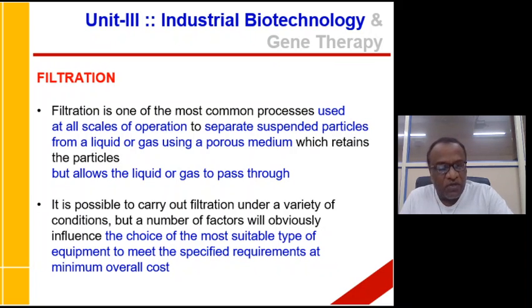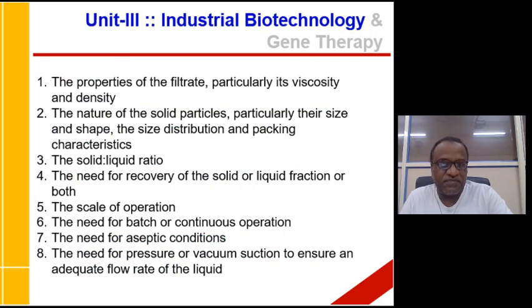It is possible, no doubt, to carry out filtration under a variety of conditions, but there are a number of factors which obviously influence the choice of the most suitable type of equipment to meet the specified requirements at minimal overall cost. Now, what are those influencing factors? Number one, the properties of the filtrate, particularly with respect to its viscosity and density.